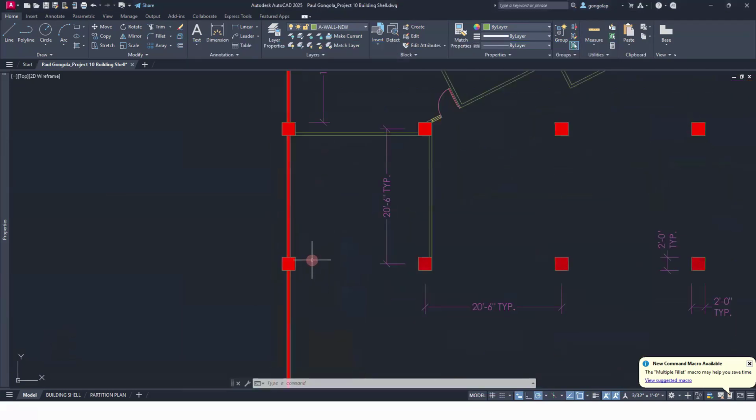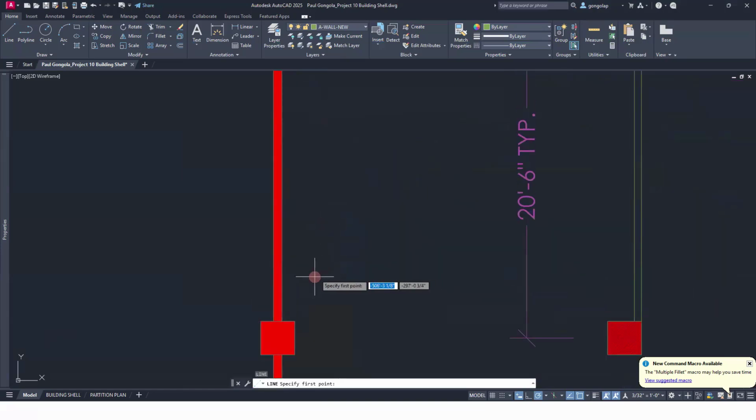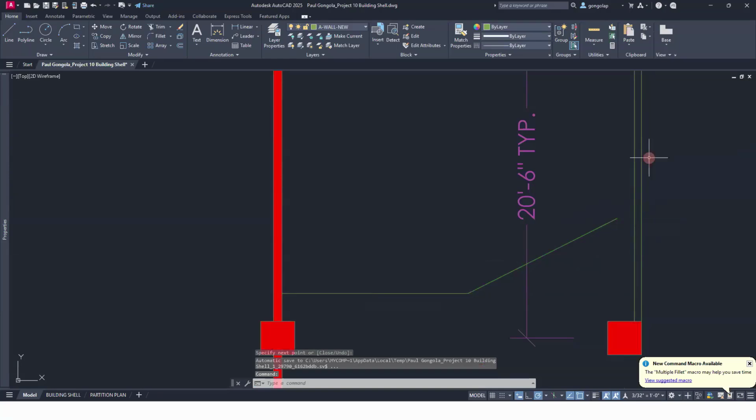So I'm going to O-track up 1'8", go over exactly 11 feet. So there's that corner there. And now there is the 27 degrees. I'm just going to go this much. I'm not quite touching it. Then I'll fillet it and I'll get it exact.